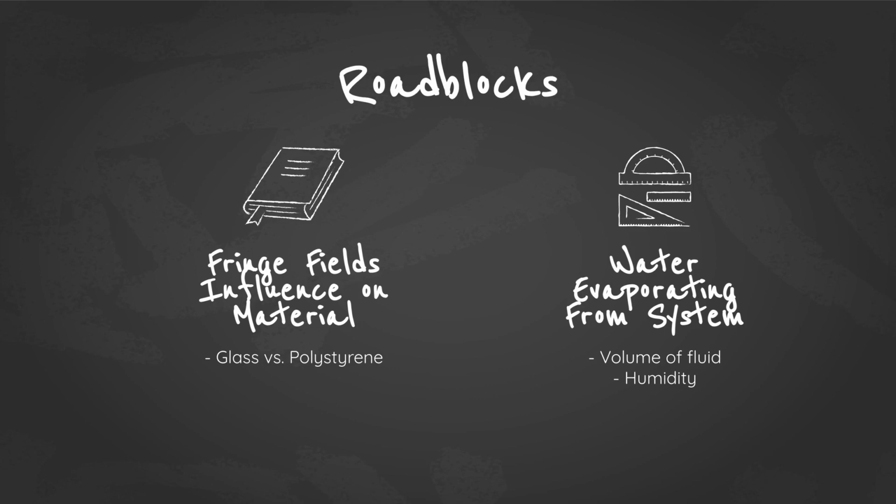Polystyrene has a lower dielectric constant, almost that of air. It is probably twice as much as air, while glass is almost 6 to 8 times more than air. So by reducing the value of our dielectric constant, yes, polystyrene will still contribute to the capacitance, however, it will contribute less and we will have more accurate measurements.